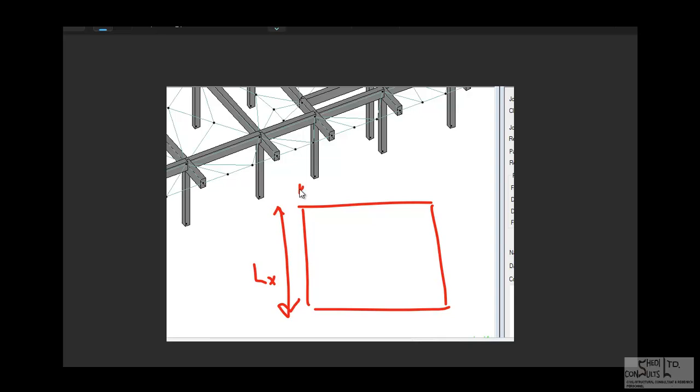The definition is explicitly contained in Eurocode 2. It talks about the aspect ratio for the slab. Once the aspect ratio is less than 2, that slab is assumed to span in two directions, so the deformation of the slab is in two directions. That's when the slab is categorized as a two-way spanning slab.